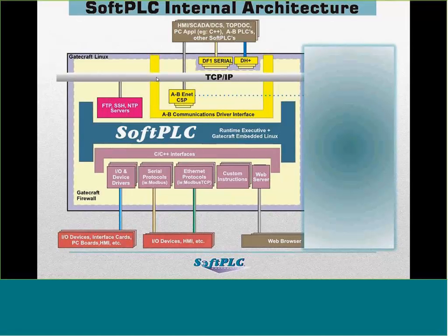Additionally, there's a TCP/IP stack in the Soft PLC which provides access to services like FTP, SSH, or NTP for Network Time Protocol time syncing. So through the FTP and SSH servers, from the network, you have access to the Soft PLC flash, so you can do remote updates of files, access reports or text files or log files that the Soft PLC may generate, firmware updates, update the web pages that are embedded into it, and that sort of thing.